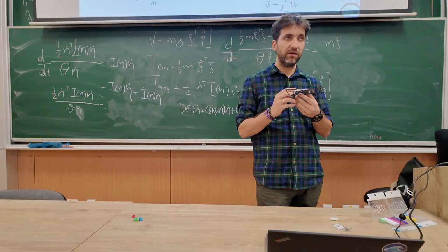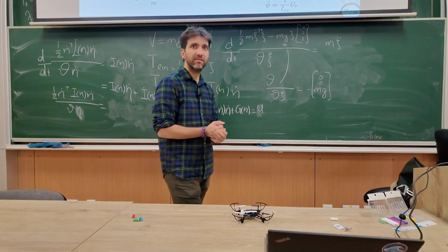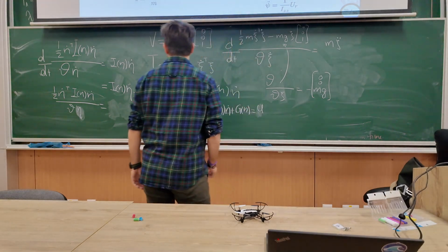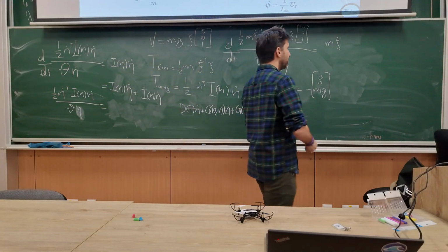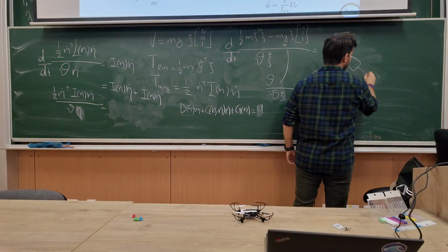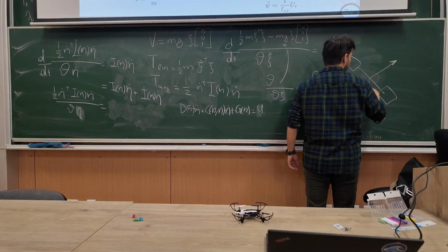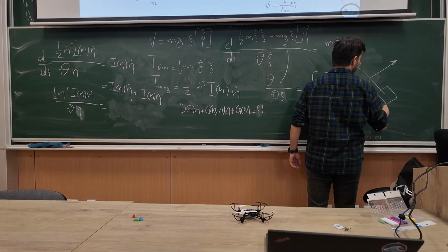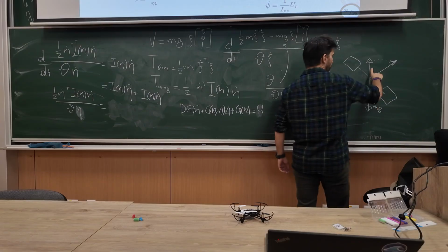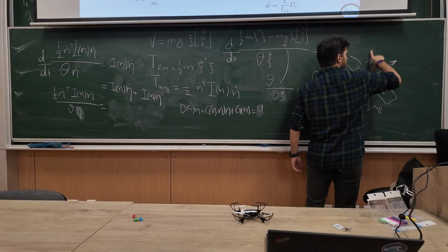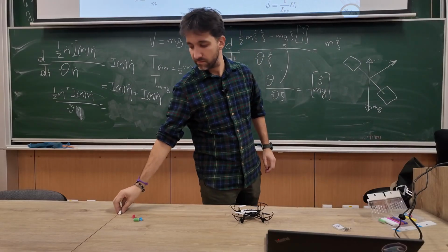Compared to the, yes, I think you do. Yes, why? Because when you change your angle of attack, the thrust vector doesn't point perfectly. Exactly. So when you rotate, your thrust vector looks like that, and your gravity still looks like that. So basically, if you want to counteract this gravity, you need to have a bigger vector here.